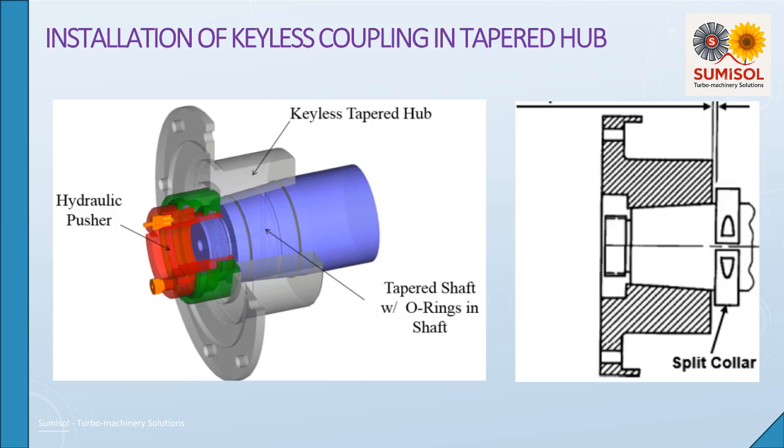To ensure satisfactory performance, the following procedure is recommended for proper installation when using the hydraulic pressure method. Step 1. Check for proper contact. Tapered bores shall be checked by using the plug gauge from a matched plug and ring gauge set provided by the purchaser. A light coat of bluing shall be used for the check.